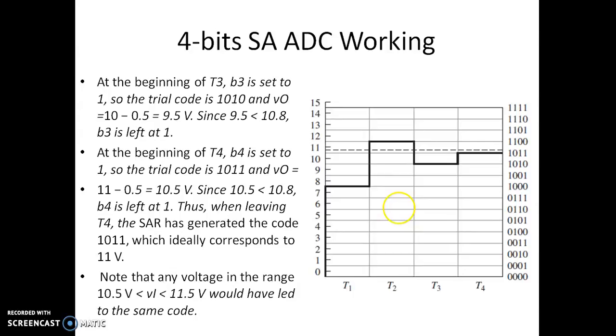So it will always take that many clock pulses. Suppose it is a 16-bit ADC, it will take only 16 clock pulses to evaluate the digital output.